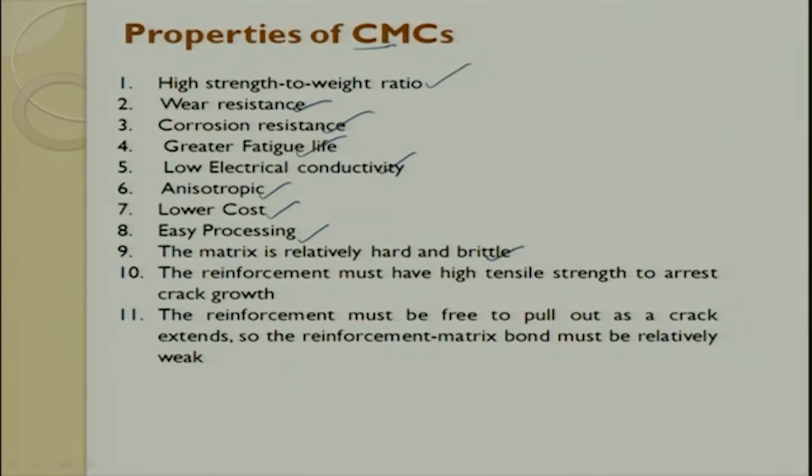The matrix is hard and brittle. The reinforcement must have high tensile strength to arrest the crack growth. This is very, very important. Then the reinforcement must be free to pull out as the crack extends. The energy, when it propagates, should spend enough energy to pull out the fiber or the particulate. Once it pulls out, the energy is dissipated. At that point the crack does not grow, and the material lasts for a longer time.